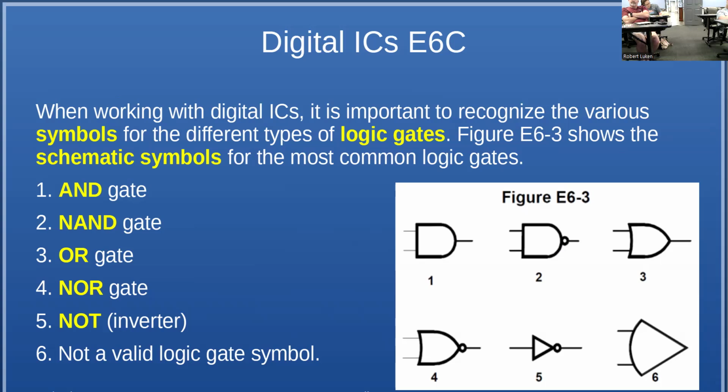And then we have a device which, if it didn't have the little circle, would be a buffer. No, not a diode, a buffer. Whatever you put in is what you get out. If it's a one in, it's a one out. A lot of times you use those to increase the current or drive. If you have it with the inverter symbol, which most of them come packaged like that, like 6 in a package, they're all inverters. So if you wanted to do straight through, you'd have to put two of them together. It inverts. So if you put a 1 in, you get a 0 out, or 0 in, you get a 1 out.